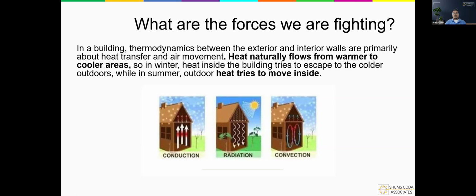And so we have here on this diagram, we have conduction. We can see that what conduction is, right, is passing through materials that allow for conduction. That's why we talk about thermal conduction in terms of our thermal envelope. How much conduction can steel or wood actually provide to allow heat into a space and transmit it through the wall cavity or through the ceiling cavity?